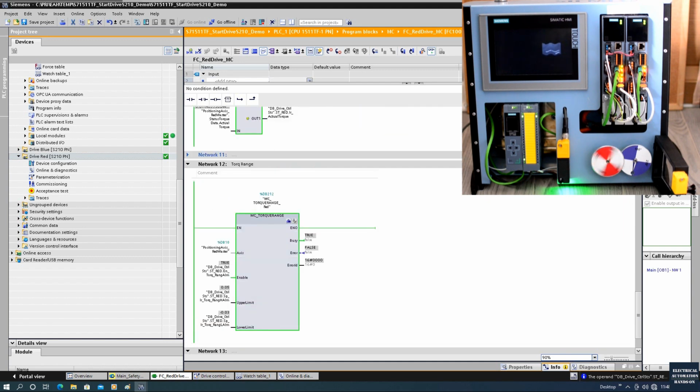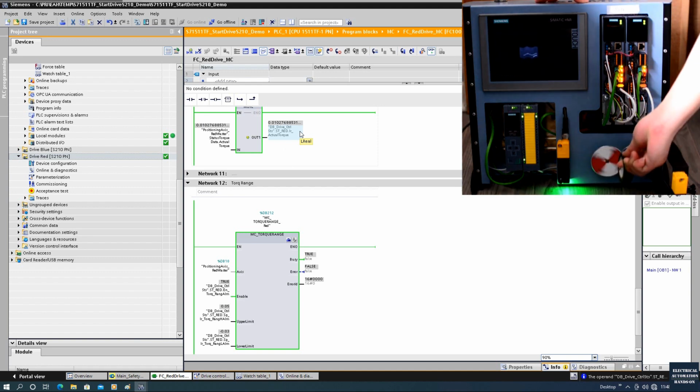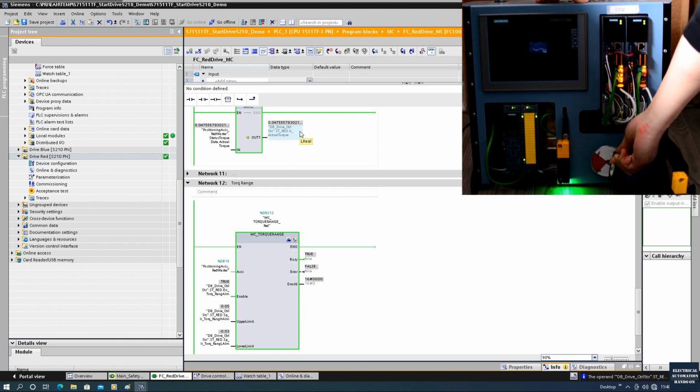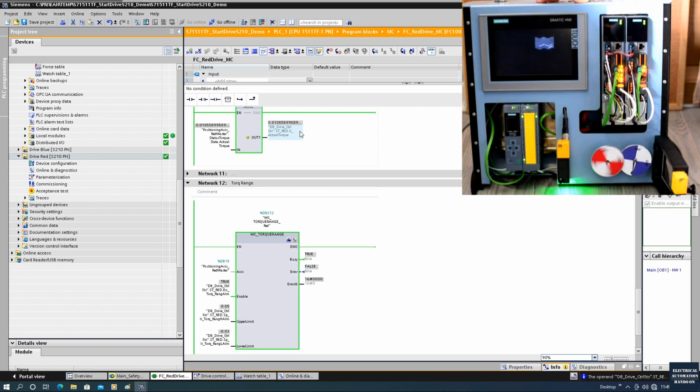And now I will block this motor and let's see. Ideally, once I block, the torque should show 0.05. And once I release, the motor just starts to run. Block, hold. So we can see the torque is showing 0.05. It's at this limit. And once I release, it just runs freely. Okay, there's no catch-up speed, no flying.